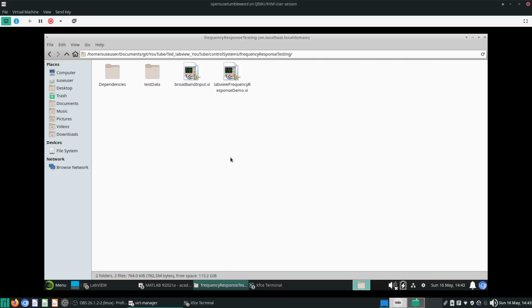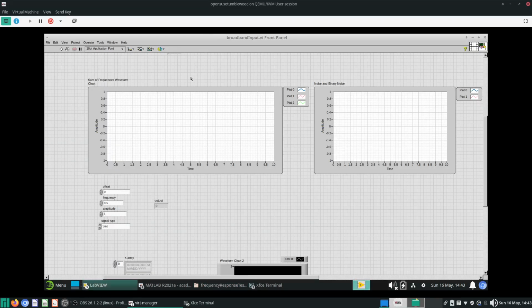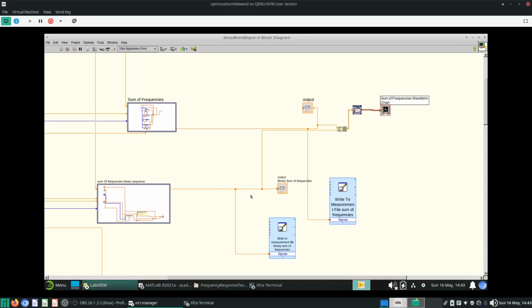Okay, so now let's talk about something else. I was saying last time that you probably want to test more than one frequency at one go. Because frequency response testing, especially for low frequencies like 0.01 Hertz, can take maybe 20 minutes. You go 1 times 10 to the minus 3 Hertz, with a very low frequency, it might take several hours just to run a test. That's not quite ideal, right? So we wanted to put many signals together, and let's show what they are like.